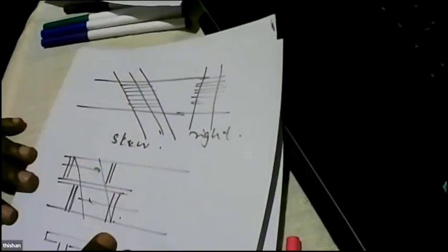I don't say that you should not design skew bridges, but with skew bridges you have to be a little concerned, because there can be certain interaction in torsion, and it's better to provide a little higher amount of small diameter bars at closest spacing.